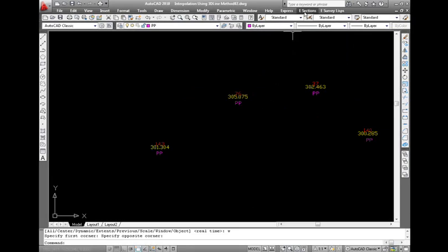Create 3D polyline by selecting elevated text, 3DT, 3JT. Text entities having z value in its properties are often referred as elevated text. Many surveying software work with 3D polylines which represent roads, canals, pipelines, etc. in a topographical map. These 3D polylines are polylines whose vertex coordinates have a z value.